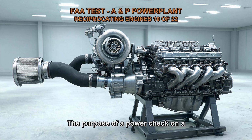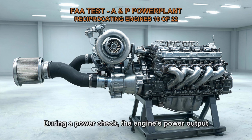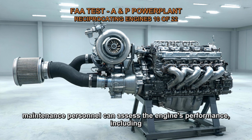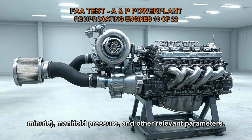The purpose of a power check on a reciprocating engine is to determine the satisfactory performance of the engine. During a power check, the engine's power output is measured and compared to the expected or desired values. By conducting a power check, the pilot or maintenance personnel can assess the engine's performance, including factors such as power output, RPM, revolutions per minute, manifold pressure, and other relevant parameters.